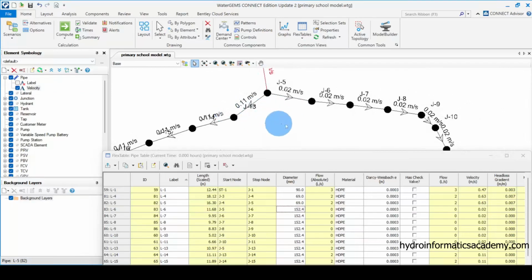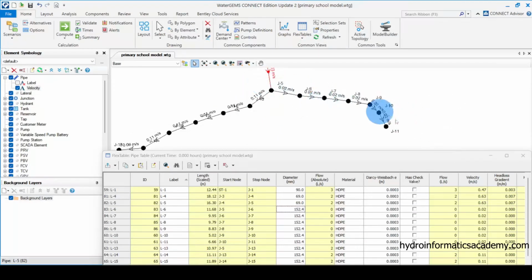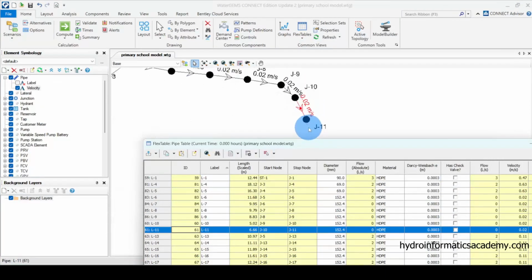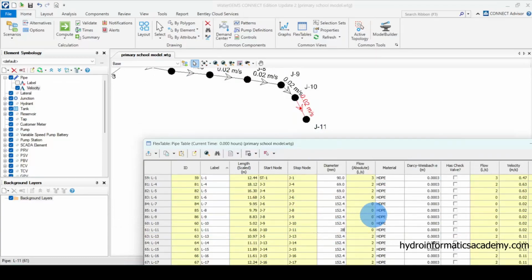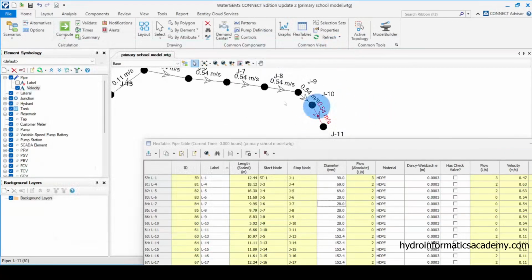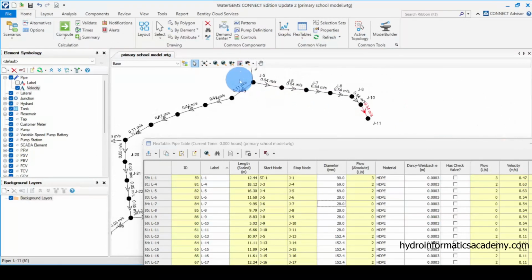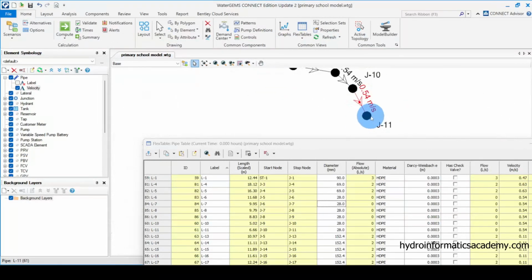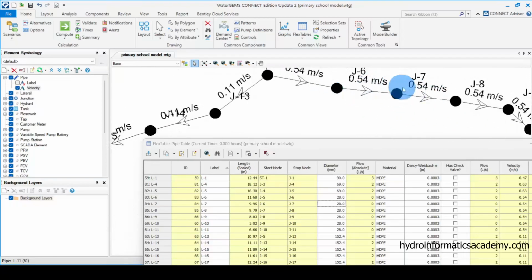And again, let me do the rest of this branch here. I want to use 1-inch pipe, just 1-inch pipe. The internal diameter for 1-inch pipe is 28. So here 28, 28, and again here 28, and here 28, lastly 28. If I run this model again and see which velocity values we have now, 0.5, which is not bad, because provided that we had a flow of 0.33 liters per second, which is not bad for our case.